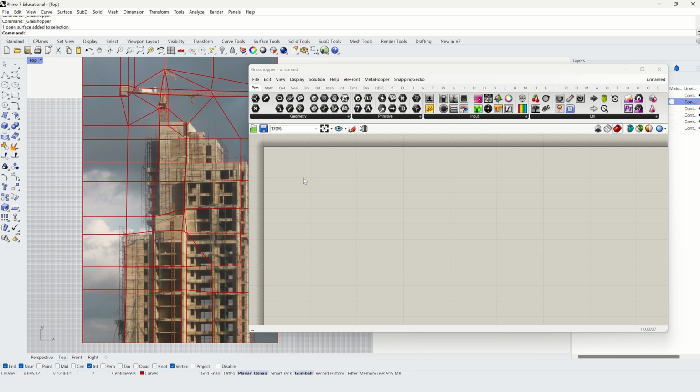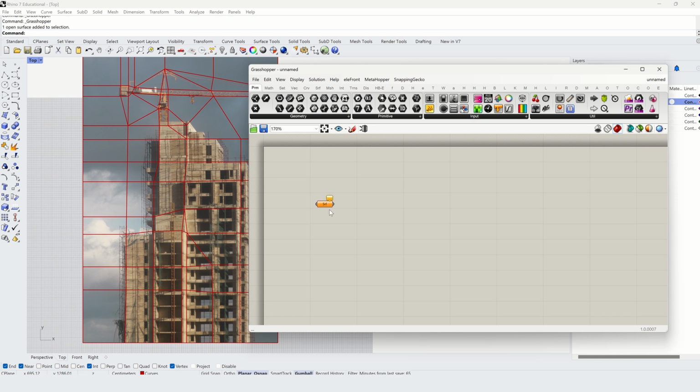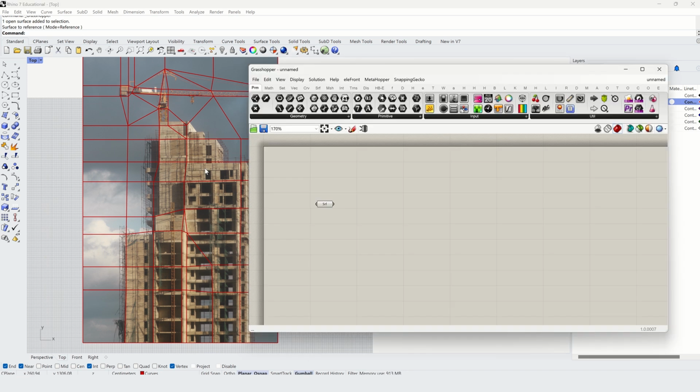To reference drawn geometry, Grasshopper uses params, located in the first tab and the first toolbar, Geometry. Select the surface param and place it in the workspace, called the canvas. It will appear orange at first, which means that it is missing data. If you hover over the component, the tooltip menu will say Empty Surface Parameter. Right-click the component, click Set One Surface, and then select the image in the Rhino viewport. The surface param will turn gray, which means everything is normal.